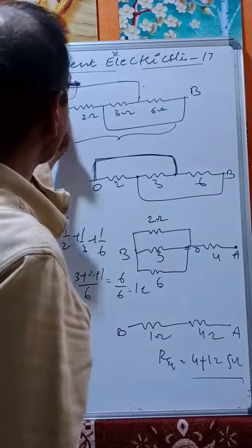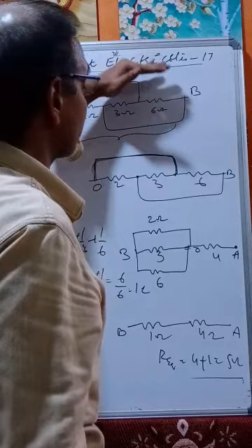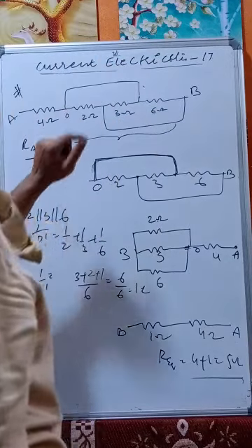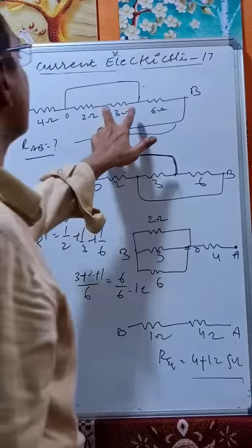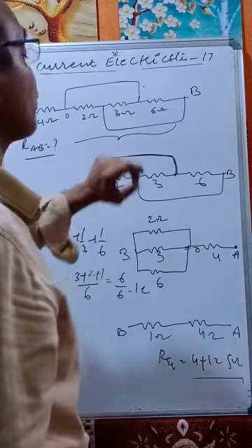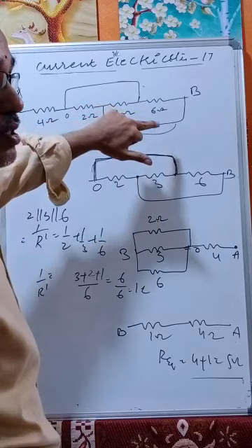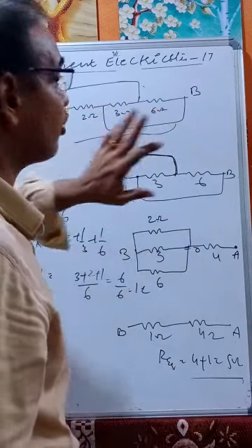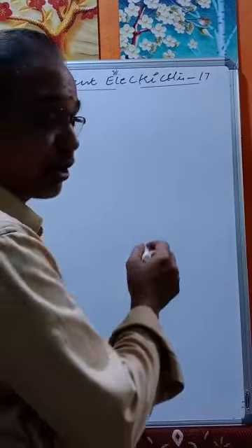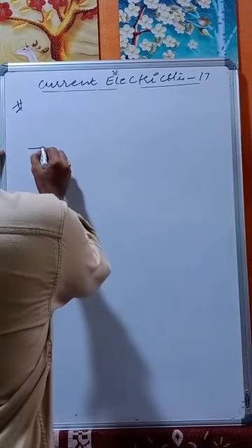Then what we have done? If you consider this circuit, lift this upwards, because this point and this point are same. Between these 2 points only we are having 2 ohms. Between these 2 points only we are also having 6 ohms. Therefore, these 3 are in parallel. If you look at the circuit carefully. Now, next model is, let us take this one like this.